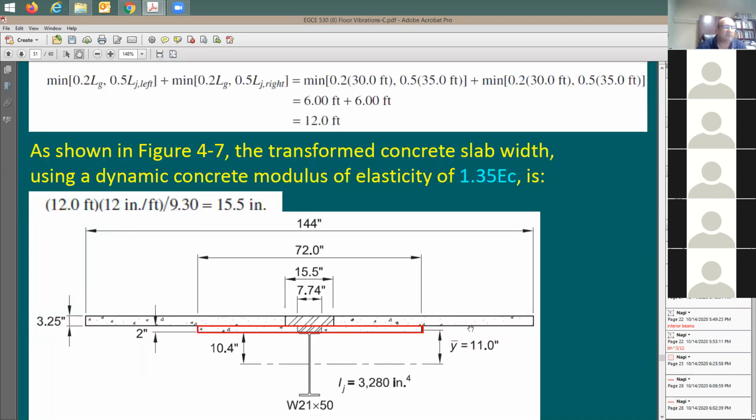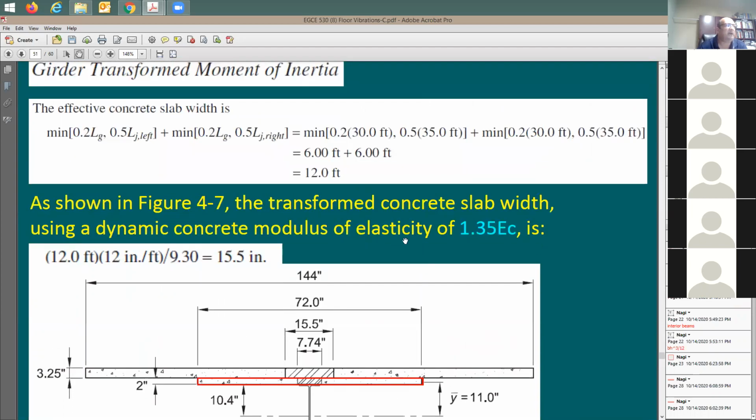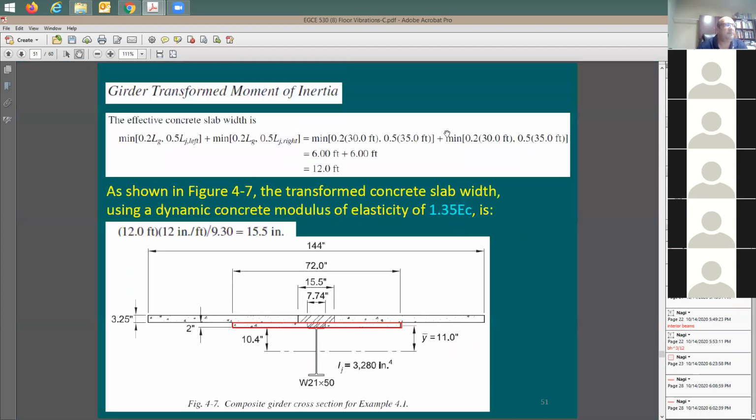So this flute that goes perpendicular to the screen, I can consider it by taking it to be 50% of the total width. So if the girder to girder is gonna be 144, right? And of course, after your analysis, you compare it to the minimum. Now we have 144 inches. Within this 144 inches, you have 72 inch, which means half of this 144 at which you're gonna have the flutes. Is everybody clear on this?